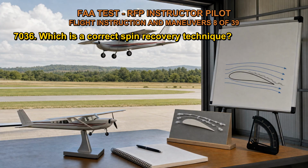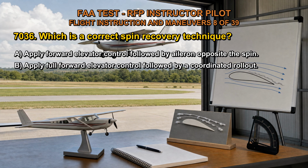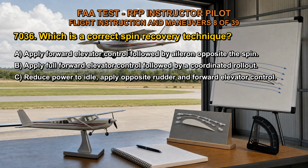7036. Which is a correct spin recovery technique? A. Apply forward elevator control followed by aileron opposite the spin. B. Apply full forward elevator control followed by a coordinated rollout. C. Reduce power to idle. Apply opposite rudder and forward elevator control. The correct answer is C.